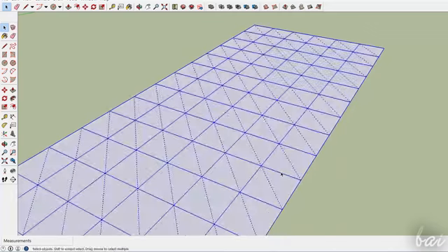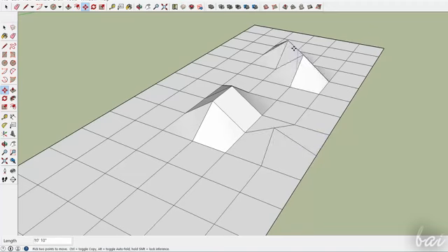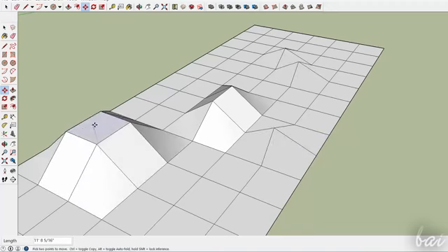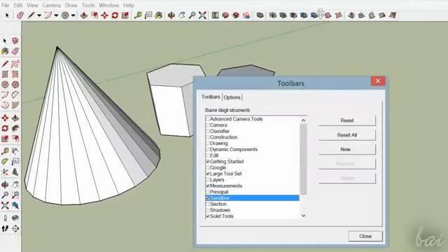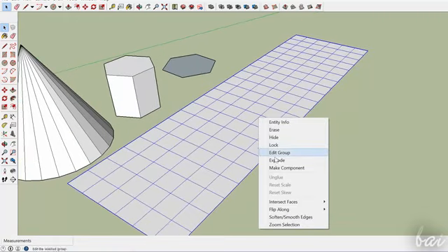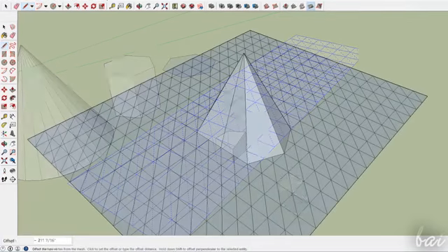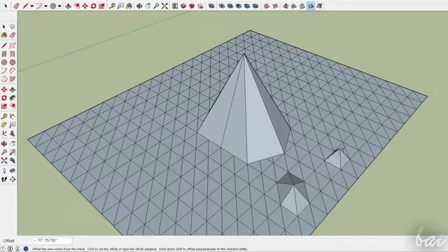In case you want to draw personalized shapes, you can use the sandboxes, also called the mesh objects. Open Sandbox in the Toolbars list. A sandbox is a mesh, such as a shape divided in lots of smaller regular pieces, such as rectangles or triangles. From this base, you can build your own personalized shapes using the Lines tool and the Sandbox tools.